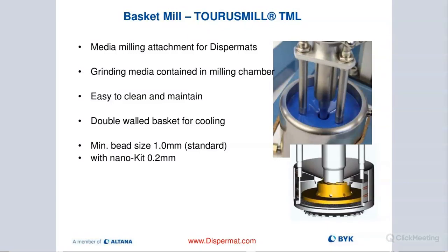And some basket mills or immersion mills actually have a screen on the side right here, and also a screen on the bottom, but the screen on the side has an issue. The problem there is that it will wear down very quickly, because that's where all of our media gets basically thrown all over the place when we are milling at very, very high velocity. So the beads will actually impact the screen on the side wall of the basket mill. And you can't cool it then either, because you have a screen right there.